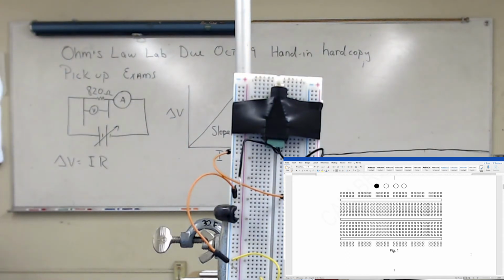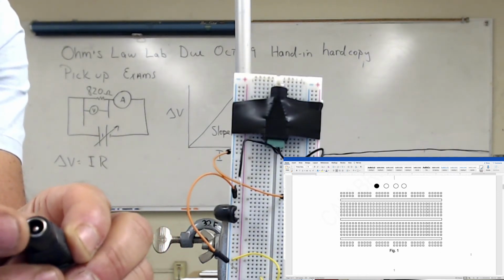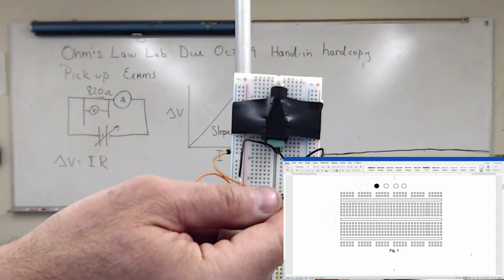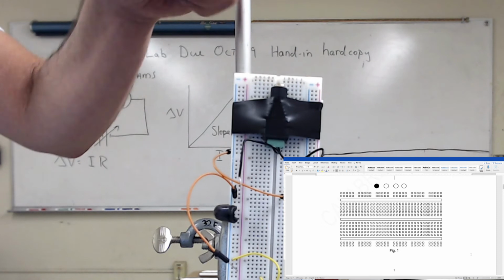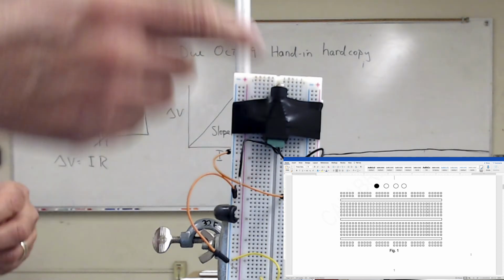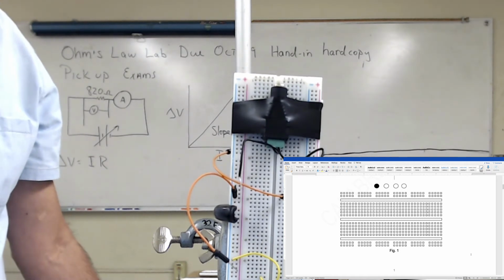If you want to know how the wires are connected to this, because those two wires are either connected to the center pin or to the outside conductor, just use a multimeter. Connect one end of the multimeter here, for example, and the other end to the center pin. If you get 0 ohms, that means they're connected together. That's your high voltage.